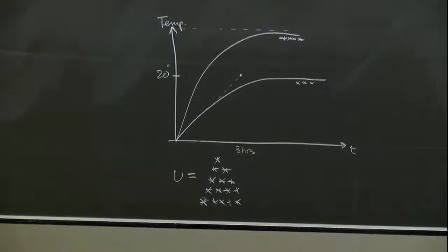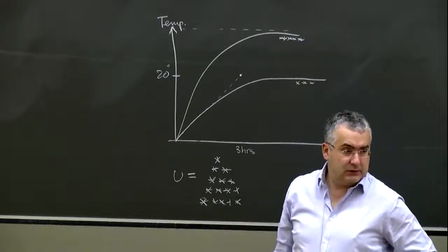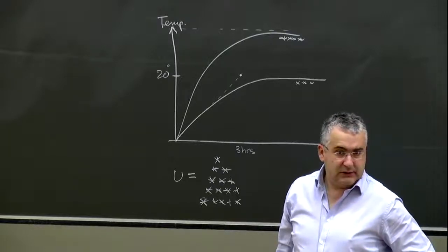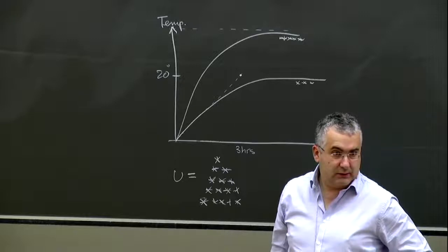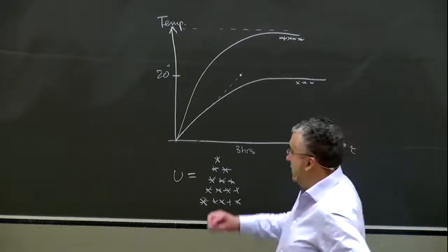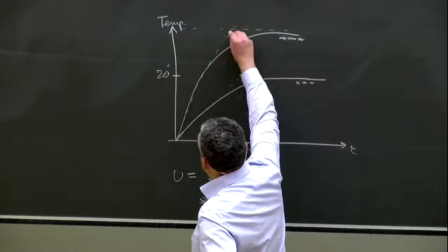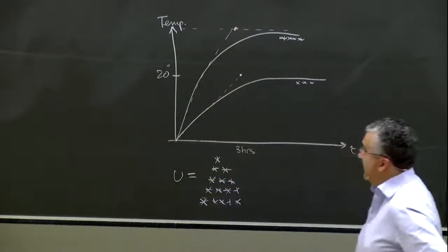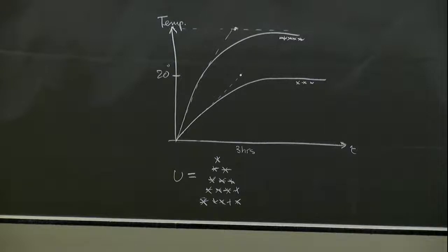But then what would you do? What do you think is the shape of these two curves? How is the shape of these two curves related to one another, assuming that the system is linear? Something you may notice is that the time constant of the system is still the same. However, since you are aiming at a higher target, you will get to 20 degrees much faster. Is that all you do? You set this to 5 and then enjoy the warmth?